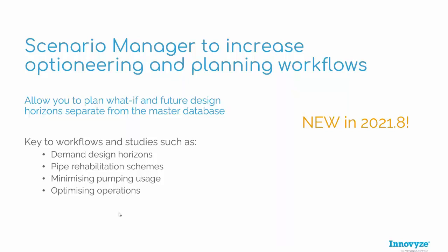We can try different options for pump usage, and as I said, you could try different set points for PRVs or valve settings to try and get the most optimal way to operate your network, and the same for future planning works and any kind of design. So if we're looking at adding in a new reservoir or a new pumping set, what are the different options, and then they can be easily assessed. So I'm going to go through a video now and briefly take you through this.